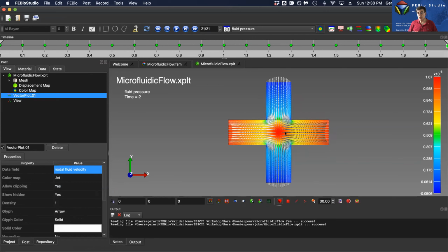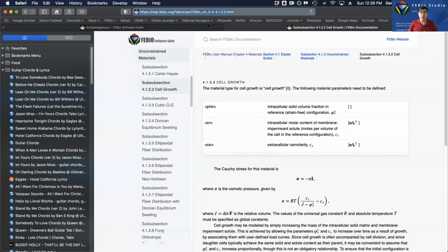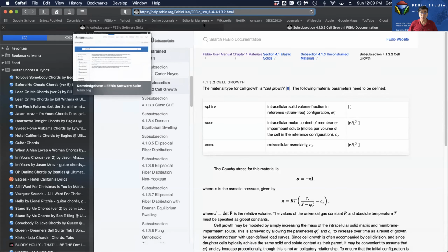What I suggest that you need to do next is to do a fluid solute analysis, meaning add a solute whose diffusivity is calculated to represent a particle that's about 50 micron in diameter, 25 micron in radius. To do this, you need to use the Stokes-Einstein relation, which you can look up, for example, on Wikipedia.